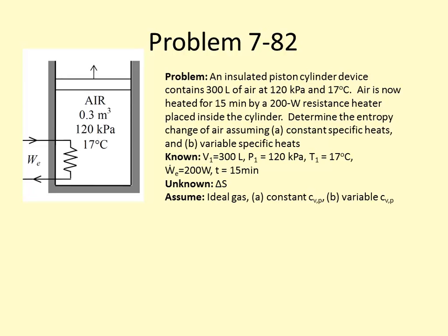Okay, so are there any questions on this problem or how to look up our reference entropies? Okay, it's very important that when you go to these tables that you understand the S superscript 0 is not the entropy at that temperature necessarily. It's the reference entropy at that temperature, but as your pressure varies, then you'll have some change in entropy due to the pressure variation as well. Because entropy is a function of temperature and pressure.